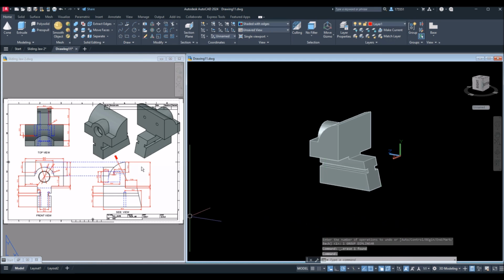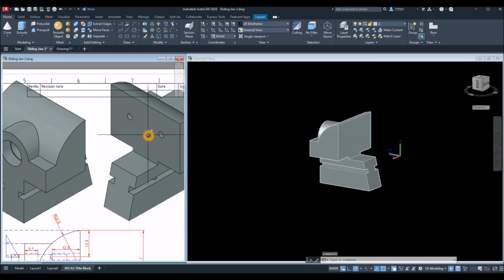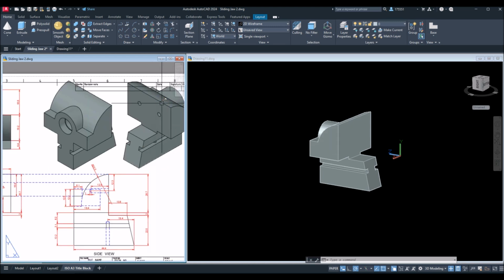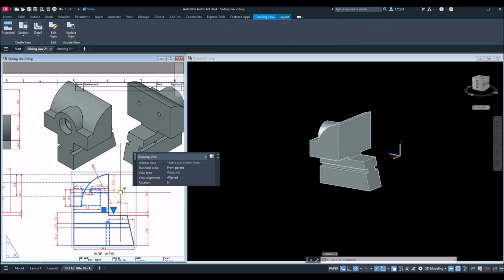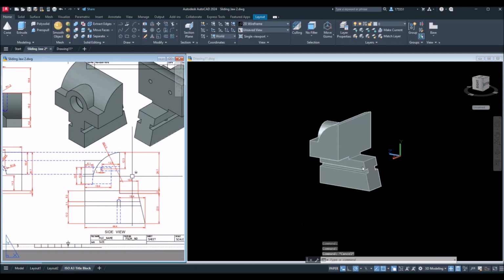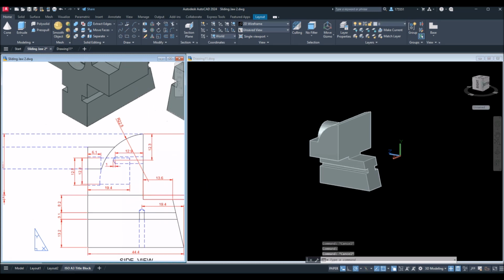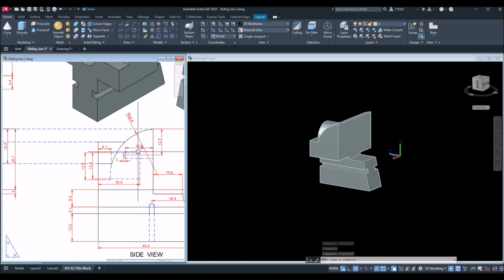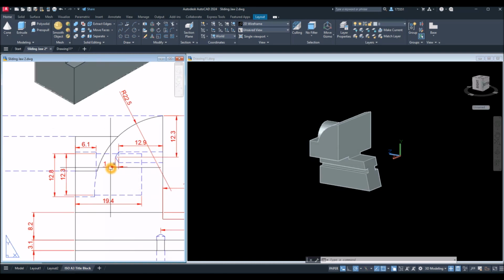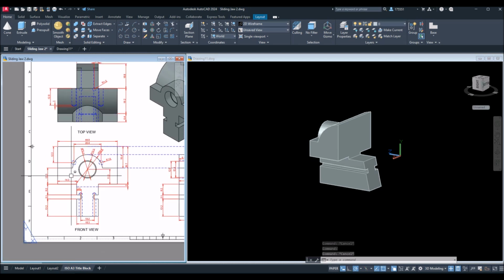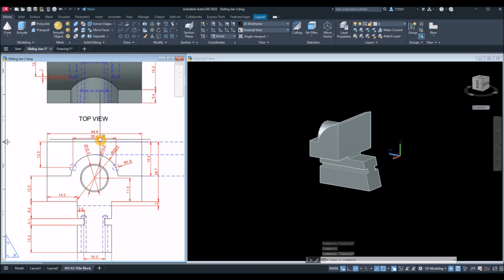The next step is to create 2 holes. Poke a hole through this face. And the distance from the top to the center of the hole is, if you look at it from side view, 12.3. And the depth of the hole is 12.9 plus the height of the cone. And if you look at the height, you can see it from here. From front view, it's 12.3. And the distance between two holes is 20.4.